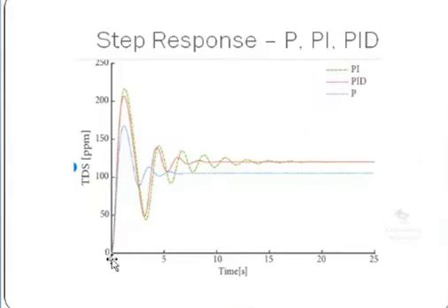See, first with the P controller, it is the blue color. The blue color is like this. It is almost reaching 100. Okay, and my aim is not to maintain at 100. It is to maintain at somewhere around 120. Okay, and I am introducing PI. PI means it is giving overshoot and it is getting settled down at the same value.